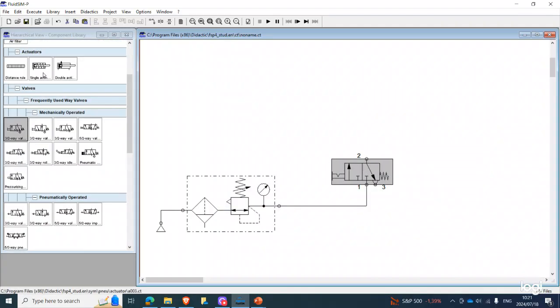So now if we get our double acting cylinder, we had a dilemma now, because up until this point we've been using the 3/2-way valve, but now if you look at the 3/2-way valve, you can see that it's not compatible with the double acting cylinder, because it only has one hole which can supply one side of the piston, and then the other side will not have supply of air, or it will not be able to take back the air